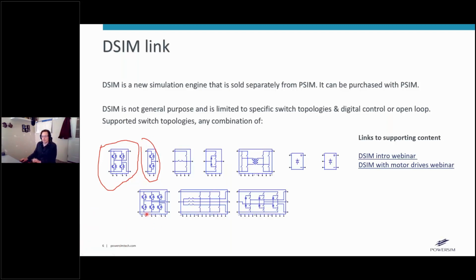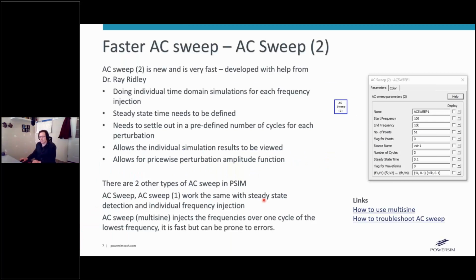Okay, back to the sweep. Where were we here? We were going to run 51 individual simulations. We're going to inject that frequency, and then measure the gain and phase at the points of interest, based on the reference frequency gain and phase.